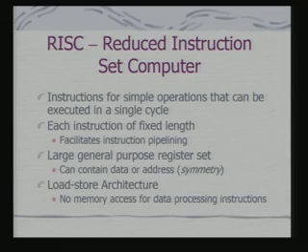It has generally a large number of registers, and these registers can contain data and can also contain addresses. We say that these registers are symmetric because they can be used for address as well as data manipulation in a similar way. Arithmetic as well as logical operations for a RISC processor always involve registers. So, the operations always involve registers and not memory locations directly.